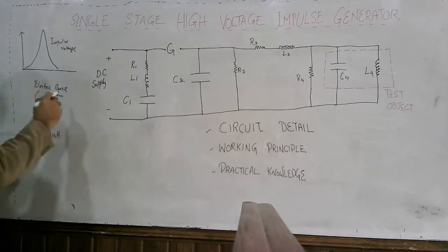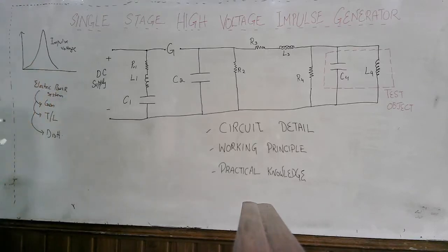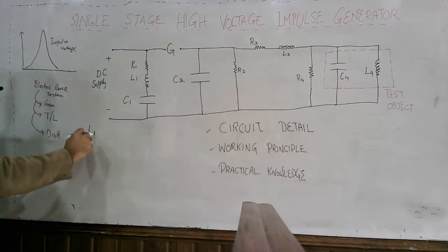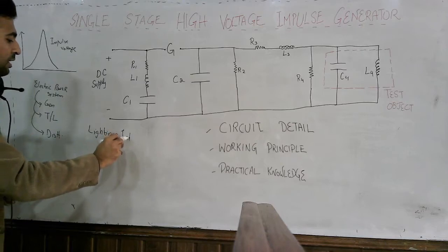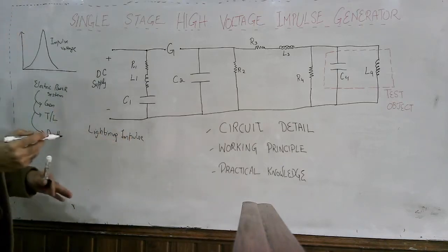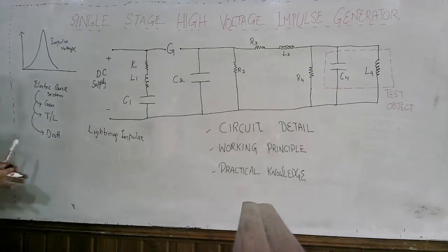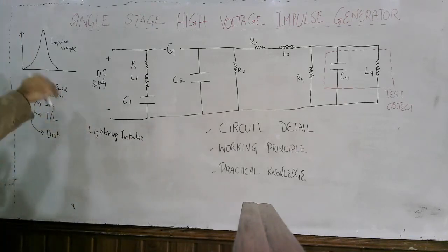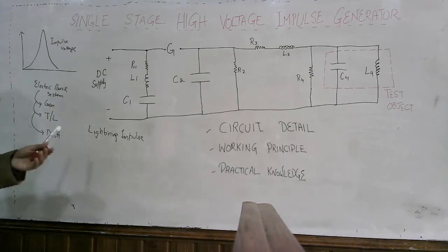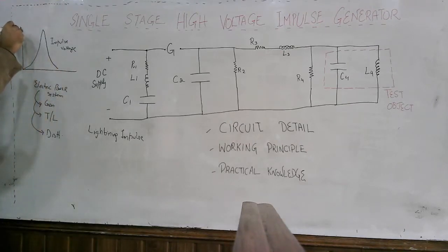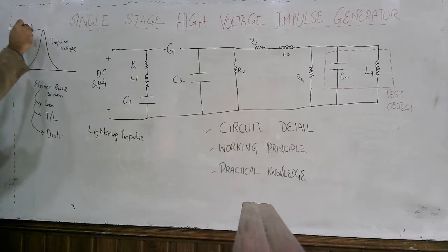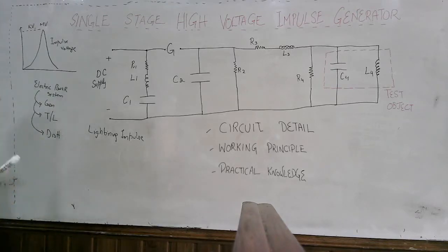Now, these impulse voltages are not normal voltages, but they are produced due to several reasons. If the impulse voltage is produced due to a lightning strike on the transmission line, then it is known as lightning impulse voltage. In the transmission level voltages, upon a lightning strike, you will observe a high impulse voltage. Impulse voltage can be in the form of several kilovolts, and it may also be in megavolts. So such impulse voltages appear in our system, and obviously, why is it dangerous?